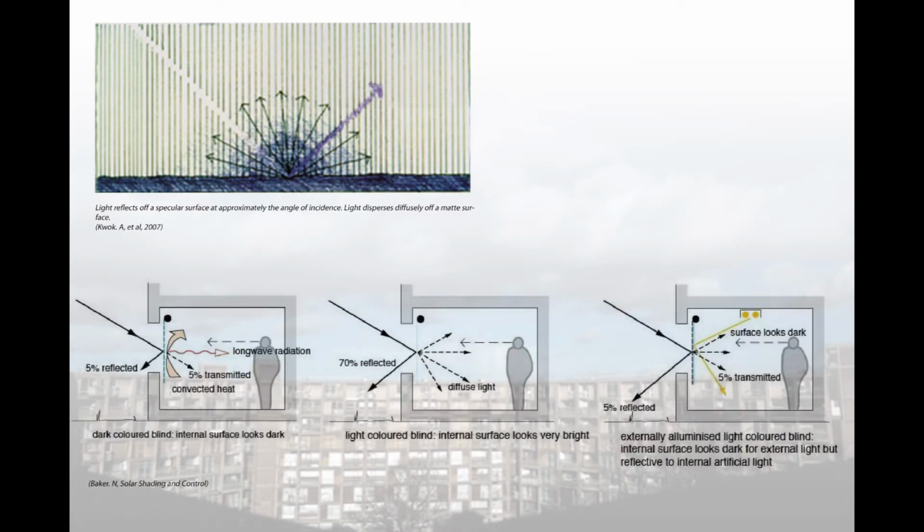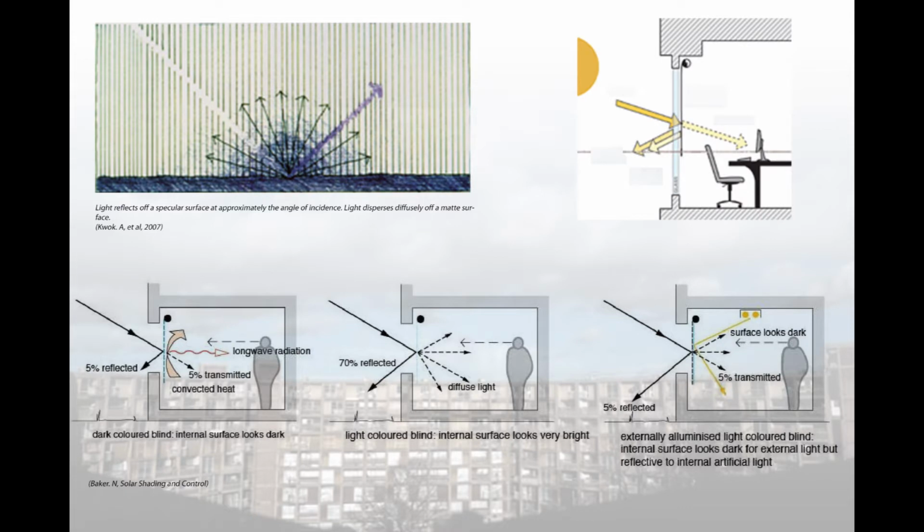Reflectancy is another important criteria. Light colour blinds avoid harsh contrast at nighttime between surrounding walls. Highly coloured blinds with non-zero transmittance may diffuse a wash of colour which can be distracting. For solar control, the side of the blind facing the window should be a light colour and preferably silvered to reflect out incoming sun.